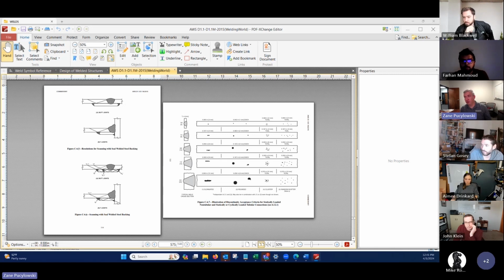The one you have to worry about is stainless. Stainless is called the galloping material. It will move all over the place on you. What you really want to do is find shops that weld a lot of stainless and ask them, what order should I go in? Should I put a backer on it? Should I put a bridge across to hold it in place while I weld it? Those are all things you need to work with your shop. I don't think we know enough to know that. If you're really worried about it, we'd bring in a welding engineer.